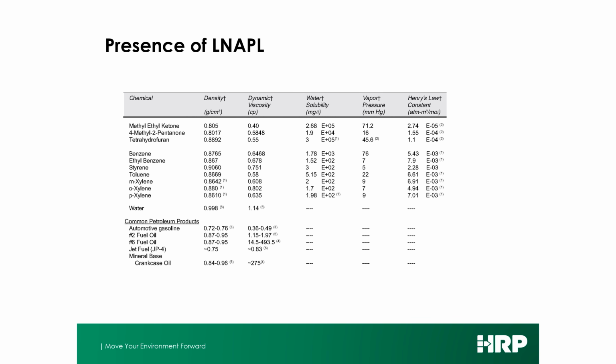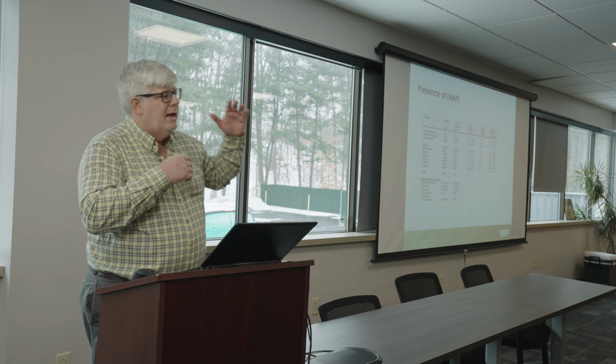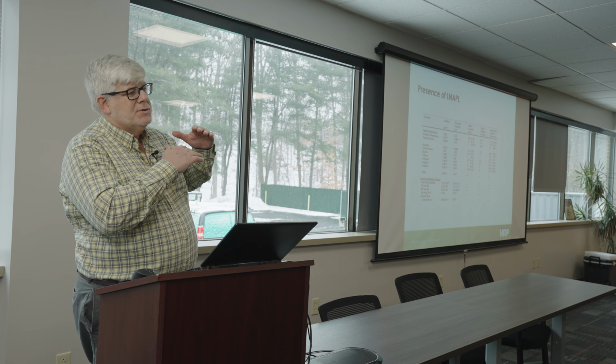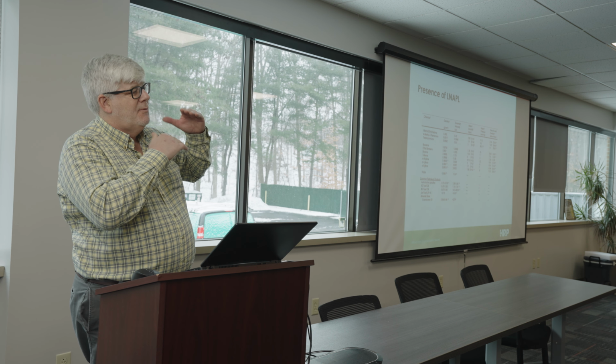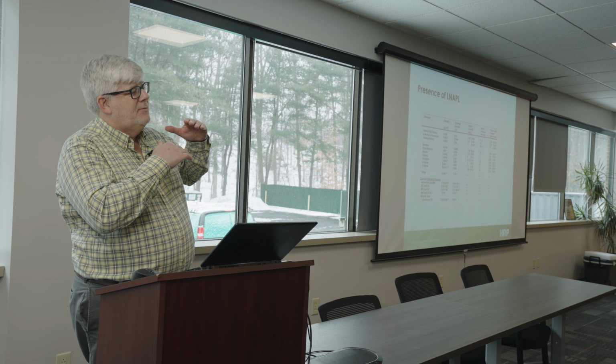If you've got floating product, we always used to call it, got LNAPL on your site, it skews the water table that you're measuring. So what you'll get back from field services, or you measure yourself with a probe, is that you'll have a depth to that floating material, that floating product, and then a depth to water. The floating product is lighter than the water, which is why it's floating. It will depress the water table proportional to its differential specific gravity.